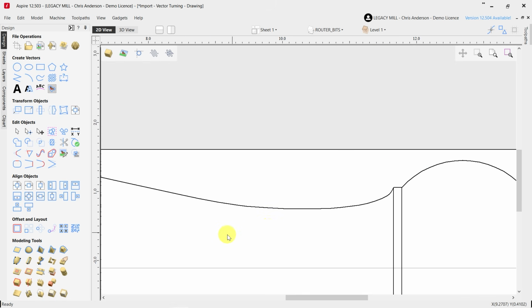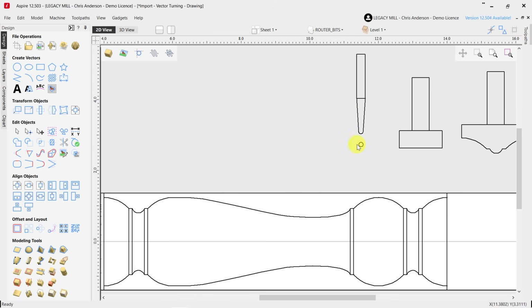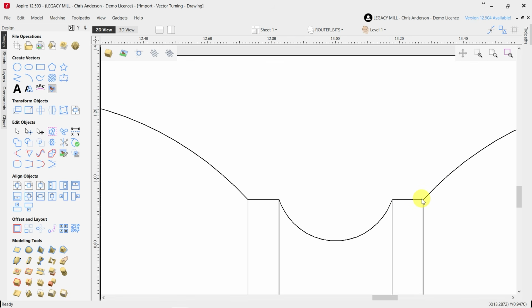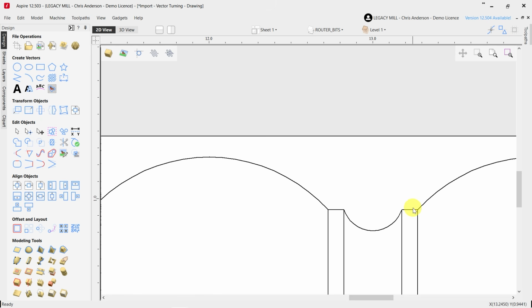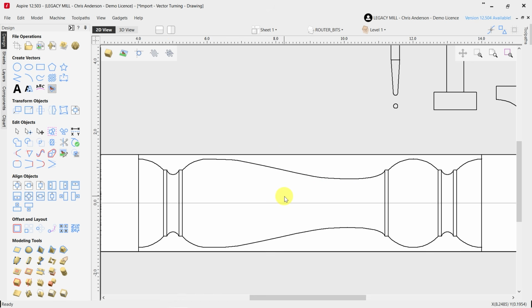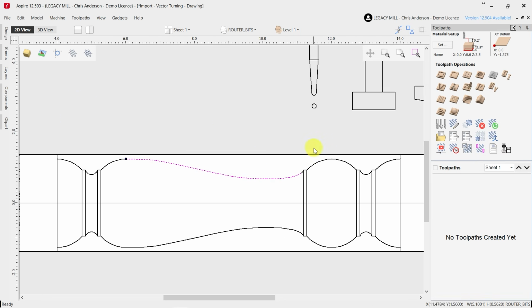Okay, this size, the 1/8 inch taper ball cutter, is a go-to for a lot of contours because it can get tighter into these kind of square crevices if my contour effect again was really unique in getting into unique shapes. Okay, this is pretty gradual, and so this will work just fine using that same cutter. So we're going to be tool pathing this using the 1/8 inch tapered ball cutter. Okay, so with that in mind, let's actually select this. And we're going to go generate an actual toolpath here in Vectric.